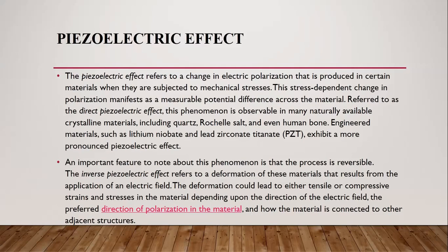As I said before, nano generators contain zinc oxide nanowires which are piezoelectric. When energy in the form of ultrasonic waves is passed through the zinc oxide nanowire, electricity is produced in the form of direct current. So by taking advantage of the fact that zinc oxide nanowires are piezoelectric, ultrasonic waves can be converted into electricity, making the nano generator the perfect device to power nanoscale devices. For a better explanation, you can read the slide here.